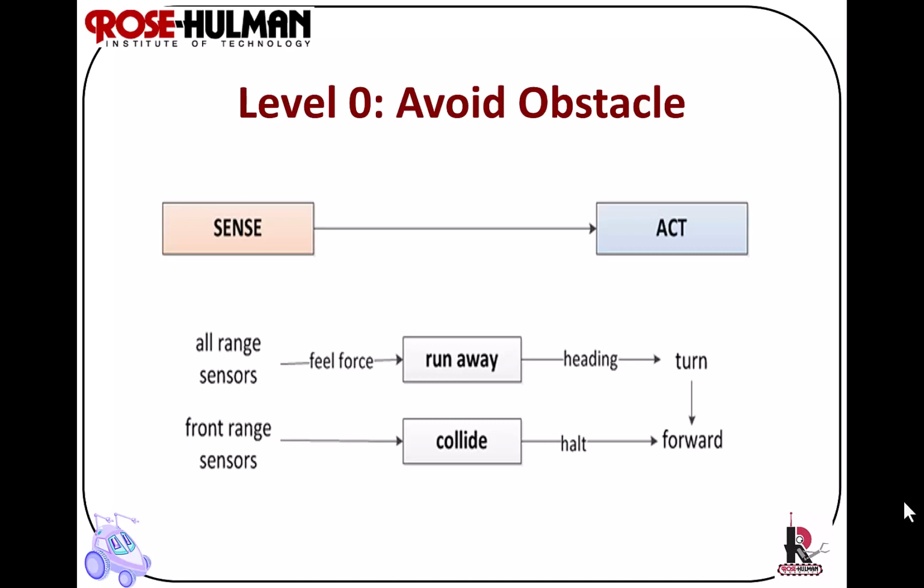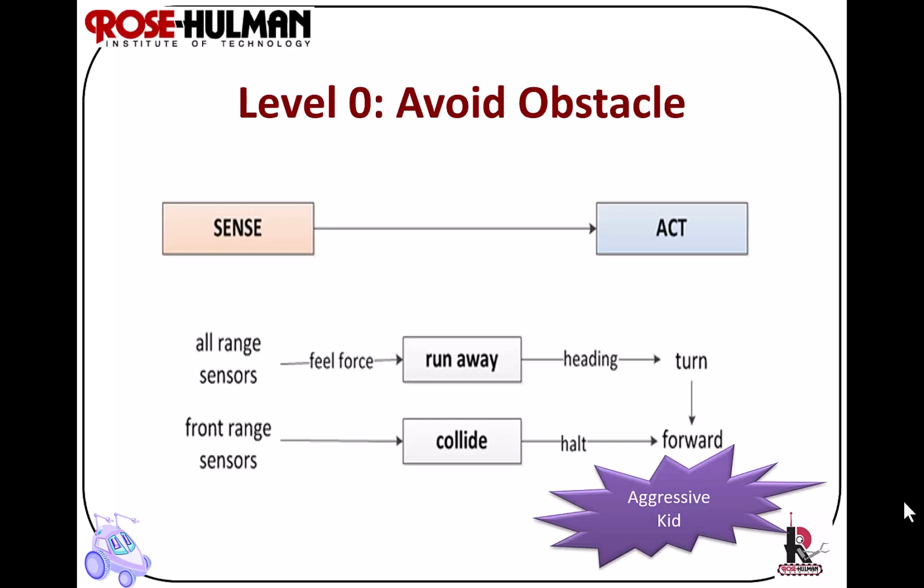So you now will dictate the robot's turn angle based upon the location of the obstacles, so it now moves away. The reason this is important is because an obstacle may not only be in the front, but it may also be in the front left, right, etc. So you have to take all of that into account before the robot moves away from an obstacle.